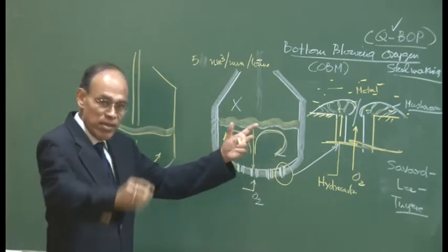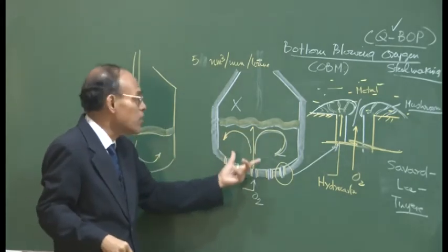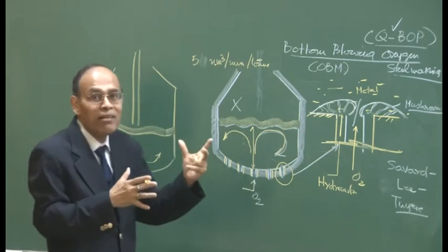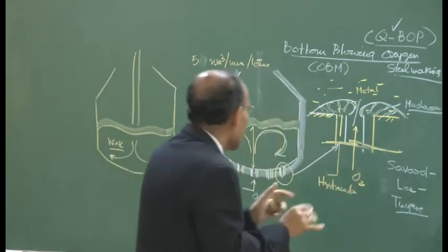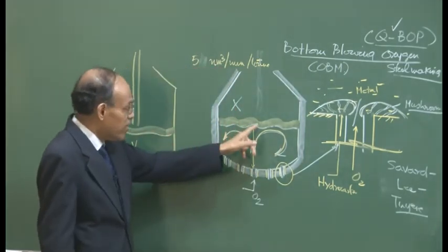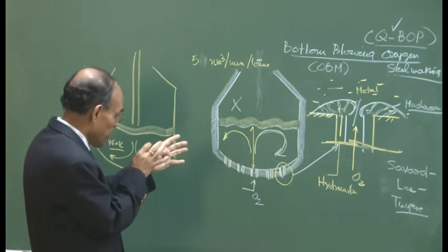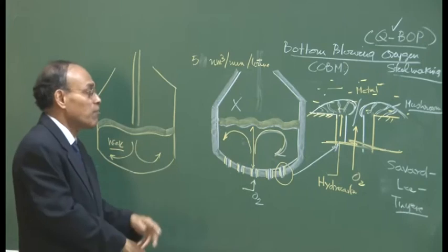So, this system is extremely well stirred, and as a result the slag metal mixing is very good, and the possibility of slag metal equilibria is far more. I would make the categorical statement that slag and metal are operating very close to the equilibrium here than it is here, at the temperature and pressure under consideration.